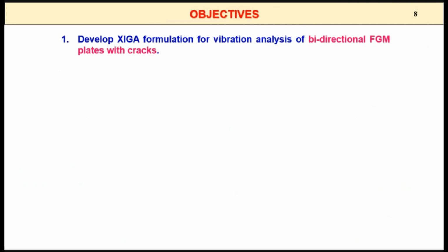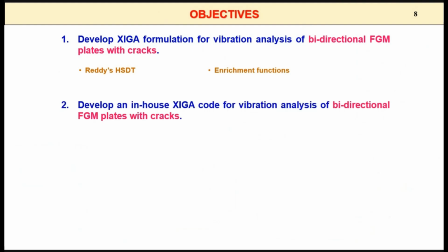So first, I developed the formulation for the vibration analysis of this plate. And I used the higher order and well-known Reddy's HSDT theory. And then I incorporated this enrichment function to model the crack. Then we developed an in-house code to perform the vibration analysis of this bidirectional FGM plate with crack.